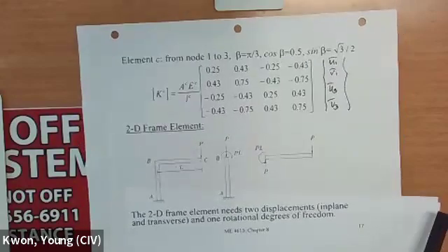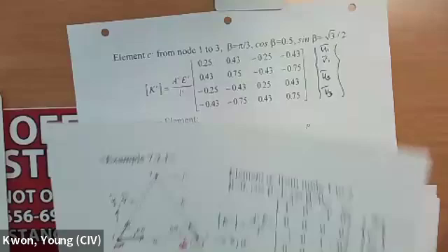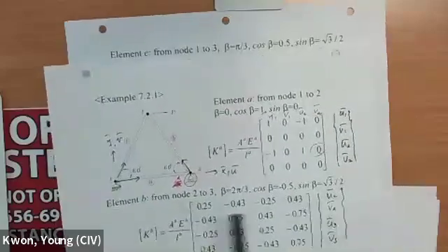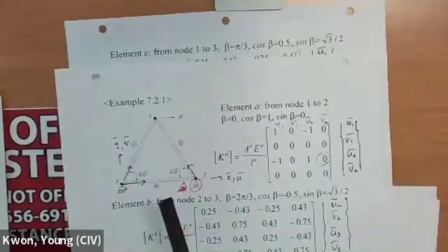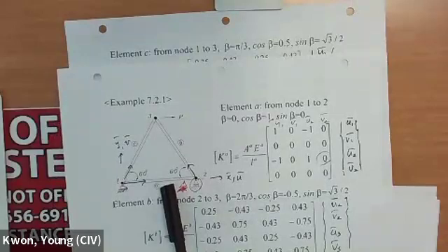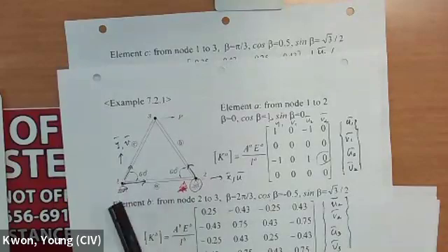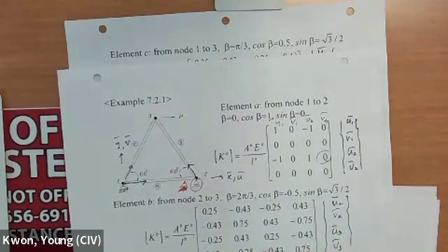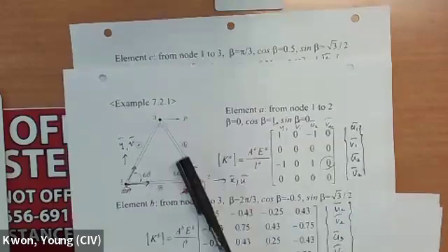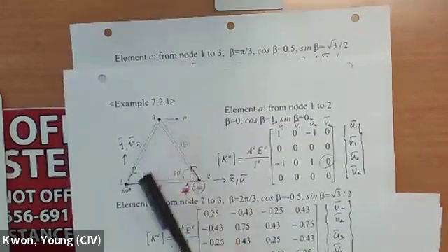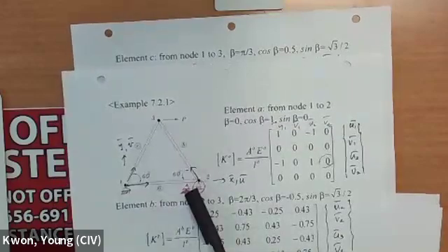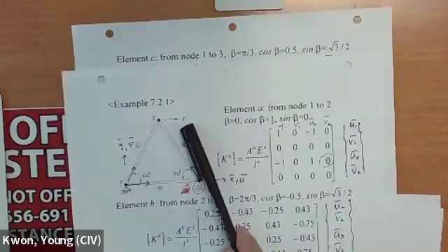So this problem, if you solve it using the finite element technique, as I mentioned last time too, since we are solving both static equilibrium as well as the deformation condition, we find not only the nodal forces at the nodal points at the pin joints, but also the deformation of the shape, how this triangular shape is going to deform because of the applied load.